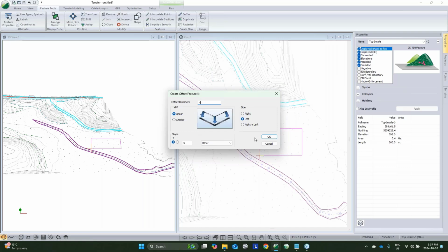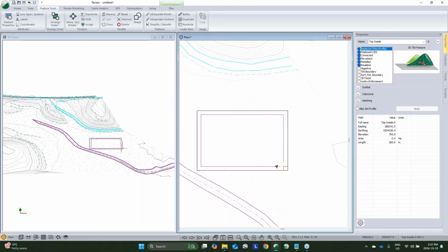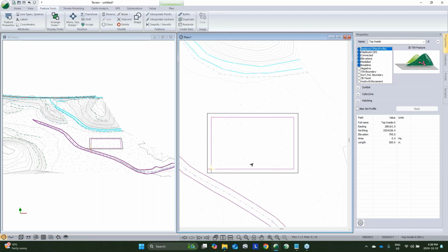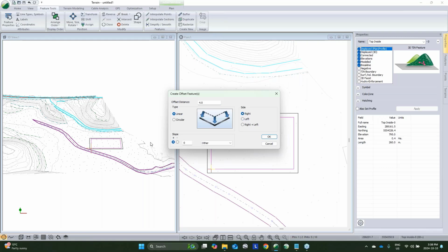We'll give it a 4-meter top. So that's also a break line. This is going to be top outside. Now for the inside of this one, we could grade to the inside. I'm going to modify buffer to the right this time. I'm going to put my buffer on a grade. And let's make this thing 4 meters deep. So we'll go 16 meters to the inside.